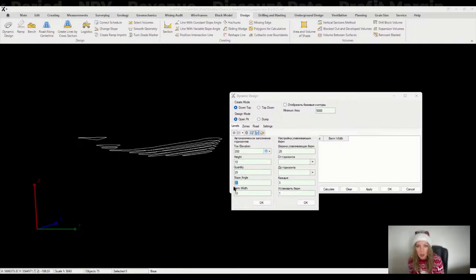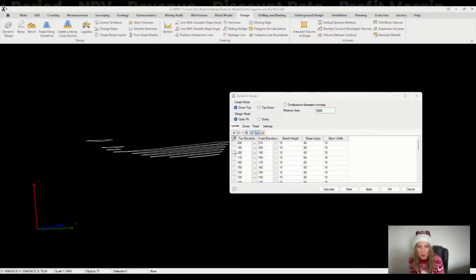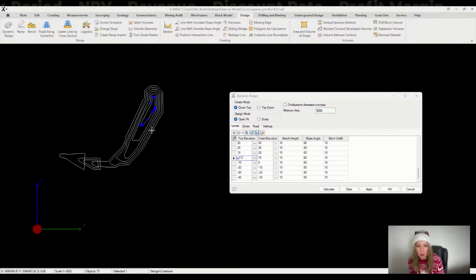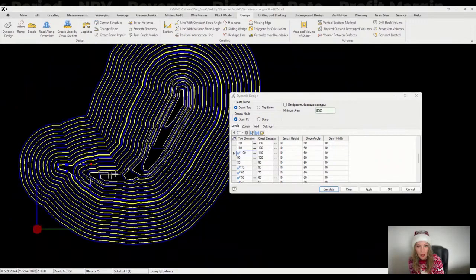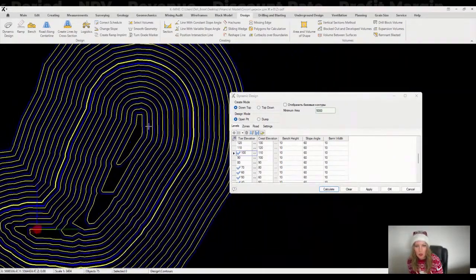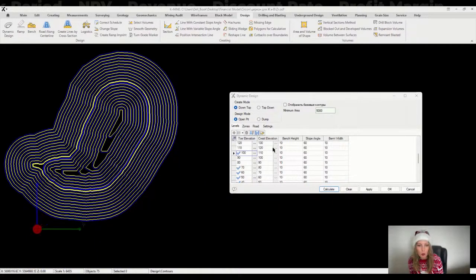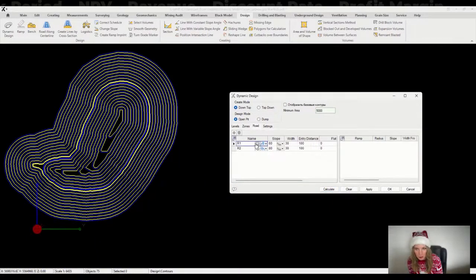Next, we match each line to its respective horizon and make the initial build, leaving out the roads for now. This will give us a pit that will later expand by adding roads. So to do this, we set up the road parameters and mark the first point where the road would start.